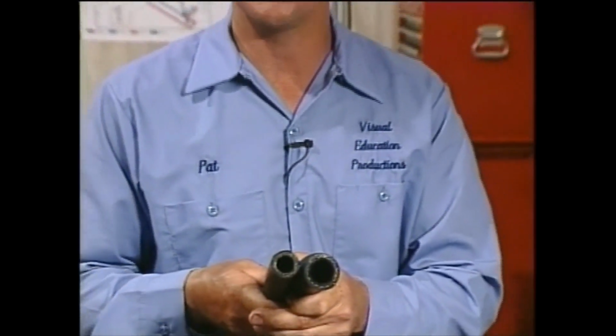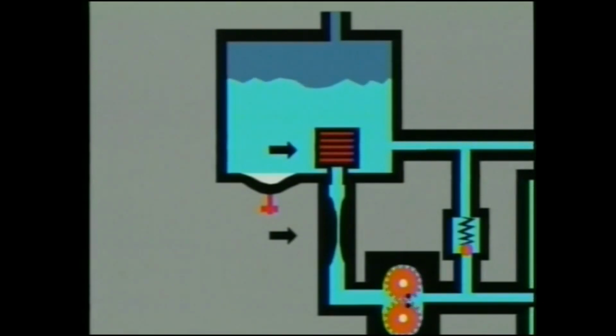Before we go on to discuss pumps, let's look at some common problems that can occur between the reservoir and the hydraulic pump. A major problem can occur when the suction filter in the reservoir becomes plugged. Excess vacuum is created in the suction hose.